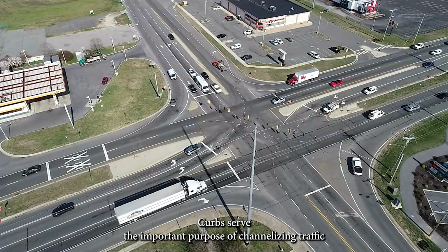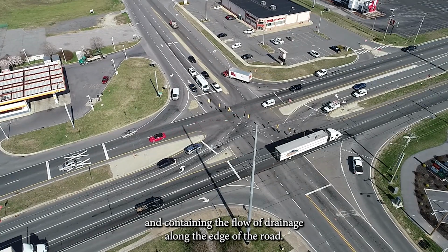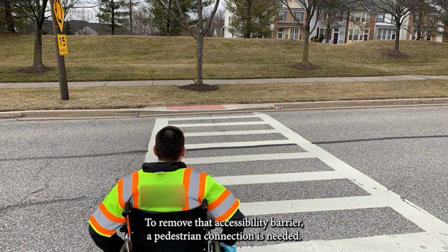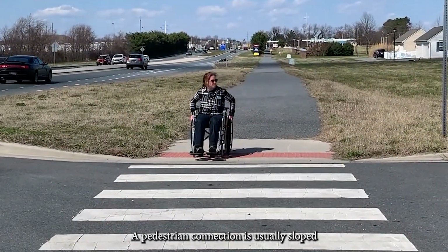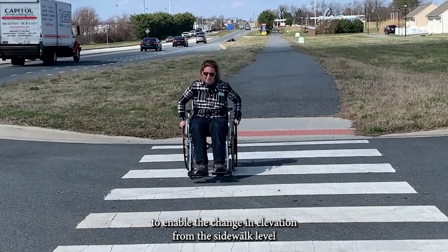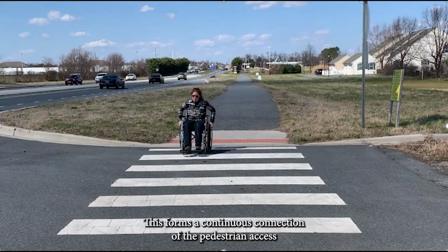Curbs serve the important purpose of channelizing traffic and containing the flow of drainage along the edge of the road. Unfortunately, curbs pose an accessibility barrier for people in wheelchairs. To remove that accessibility barrier, a pedestrian connection is needed. A pedestrian connection is usually sloped to enable the change in elevation from the sidewalk level to the street level. This forms a continuous connection of the pedestrian access route from one side of the street to the other.